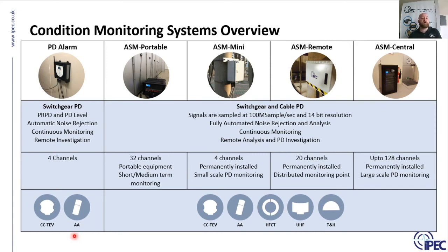So it's switchgear focused. And so if you find a problem with a handheld equipment, you can very quickly install the PD alarm. You can receive the same level of complexity. You get the PRPD, you get that differentiation, and you can also see the data remotely, either from a tablet or on your computer if it connects to a server. So that's the other advantage of the PD alarm. Very simple to install, very small device.